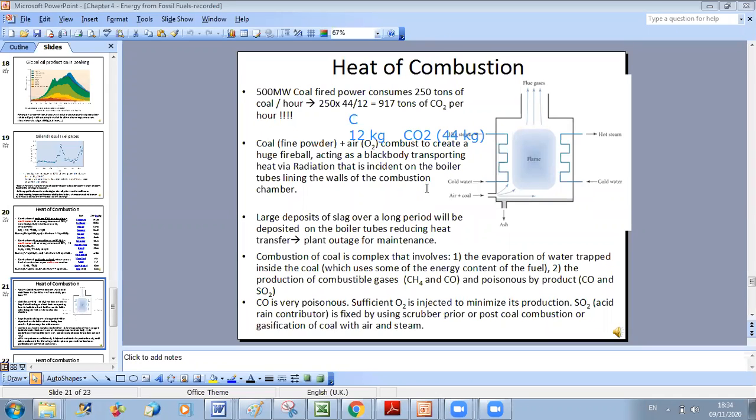So when we do the combustion, part of the energy will be lost to evaporate water. In general, when calculating the heat of combustion, we sometimes take this heat loss into consideration, because what we want is the final used energy, not the total one. What we care about is the useful energy after evaporation of water.